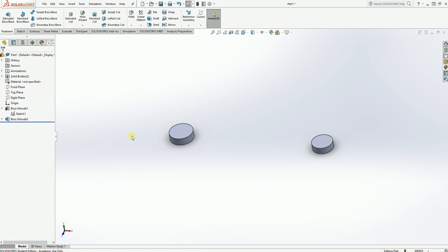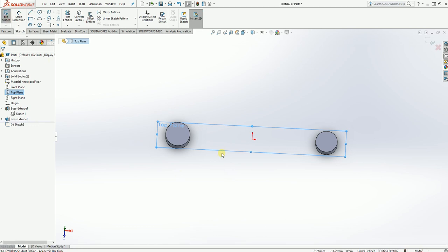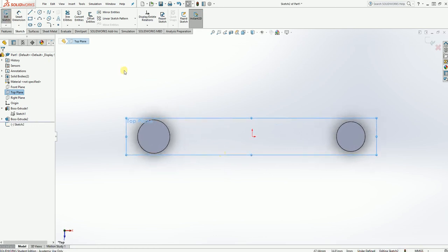Now it's important here that you remember that both of these aren't the same thickness, so they don't have the same starting point. So I'm just going to carry on working off that top plane that I selected first, because that goes through the middle. So that's a known entity, I know where that is. So extrude again on that one, just normal 2.